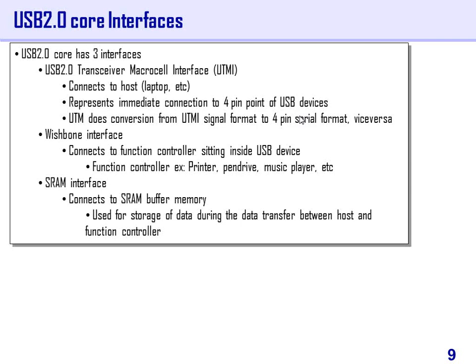If I am using 16 endpoints, or let's say I am only using 10 endpoints, do I need to again divide into 32 regions? No. It is me who is going to decide the start of each endpoint buffer: buffer 0, buffer 1, endpoint 1 buffer 0, endpoint 1 buffer 1. I should not keep too small a buffer size for some endpoint, because it will become full too quickly and become a bottleneck again.